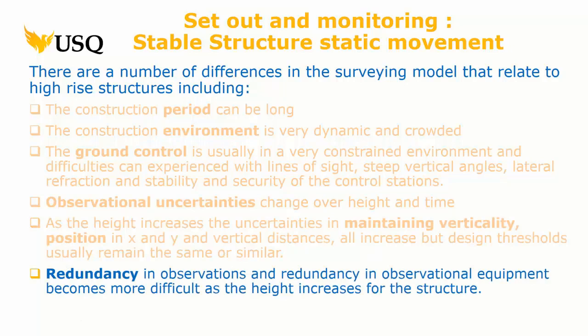And like nearly everything in surveying, probably in life as well, redundancy is the big issue, right? If you put control in and you think this should be enough, just double it. That's probably a good figure to start with, right? You are going to lose control. It might be sight lines, it might be a crane dropping 10 tonne of concrete onto the position you had before, which, if you want a new total station, is a good idea, just leave it there, right? Get the insurance. But redundancy in measurement is the same way.